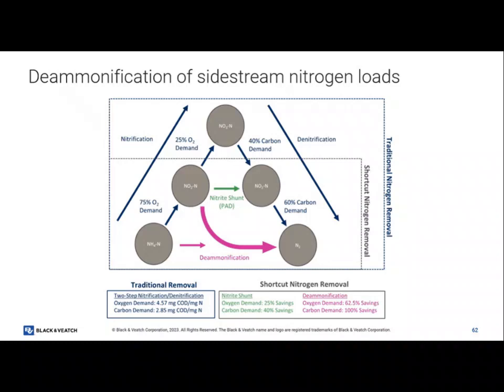Also, you go nitrite lock if you don't have enough alkalinity. Oh, that's another one, alkalinity. This is one thing that I experienced here, it went too low. And basically the first thing that stops is the second step here. So you have nitrite accumulation. I don't know if you saw that at Rowlett or not. I don't know if you saw nitrites, but you have UV there now, don't you? Oh, it's chlorine. So you might have seen, when the MBR was on, you might have seen the nitrite come up there. Paul?